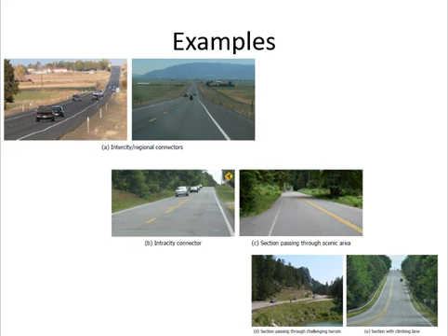Okay, and uninterrupted means what? It does not have intersections. And what was the condition when a highway with intersections can be uninterrupted? What was that condition? 2 miles. Okay, then the intersections are more than 2 miles apart. Obviously, this highway has intersections, and these intersections are very close to each other. So that's why it cannot be uninterrupted. So where can 2-lane highways be uninterrupted? This is the example of that.